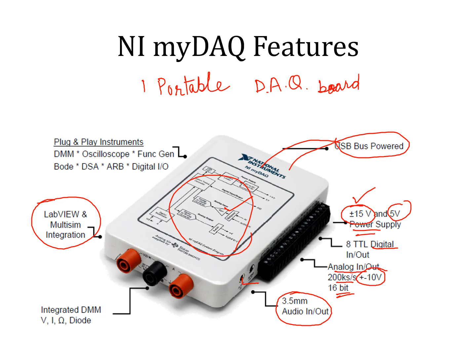So LabVIEW works as a driver as well as a GUI. So we can perform many functions, like we can convert it into a digital multimeter. We can use this board as an oscilloscope, a function generator, that is, we can generate a few functions using LabVIEW. Through LabVIEW they will come to this board, and through the board we can generate those functions either as analog output or through digital output pins. So you can imagine the power of this particular board.